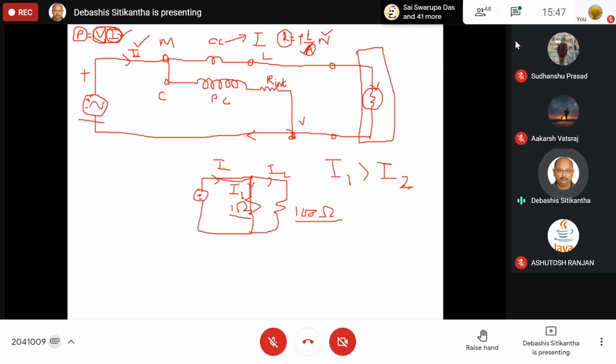Now look over here. You can see this pressure coil is connected in parallel across the load. The load is over here, and this one is connected in parallel across this load. One can say that the current coil is in series over here, so it is not in parallel with the load. But the concept is a little bit different, because as I told you, this current coil offers very low, almost negligible resistance.